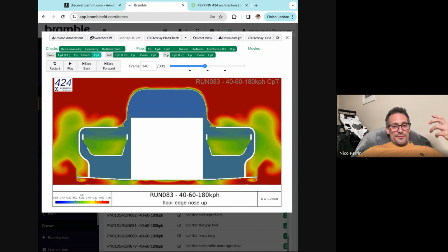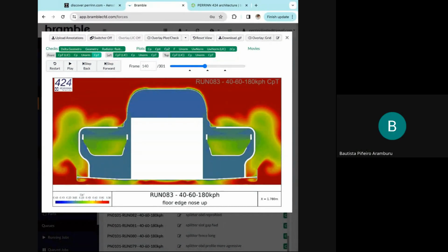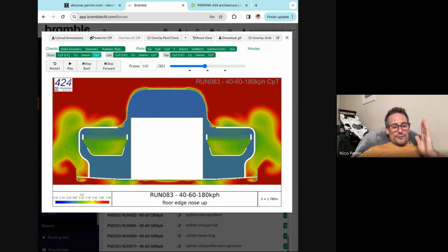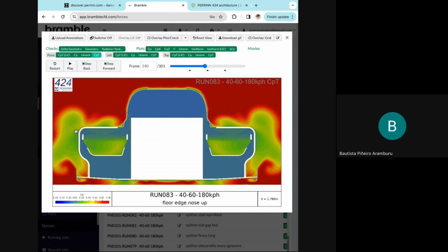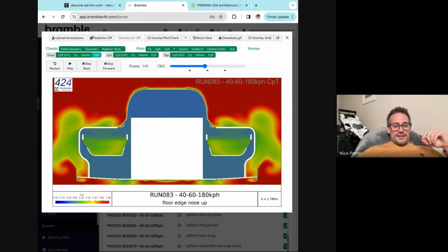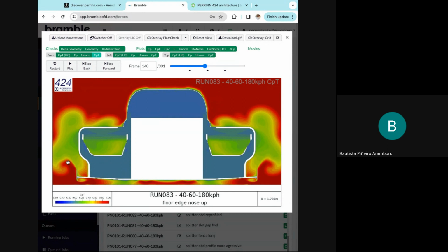It's when you have red flow, which is, again, in aerodynamics terms, high energy flow. Then if you put fences on that, or you put edges for it to turn around, it's going to create a lot of suction. If you do the same in the green zone and put, say here, a wing profile, it will be very, very weak. It will not do much. Because a fence or a profile in a low energy flow, it's the difference between having your hands inside the car or putting your hand through the window and seeing the pressure pushing on it. It's exactly the same.